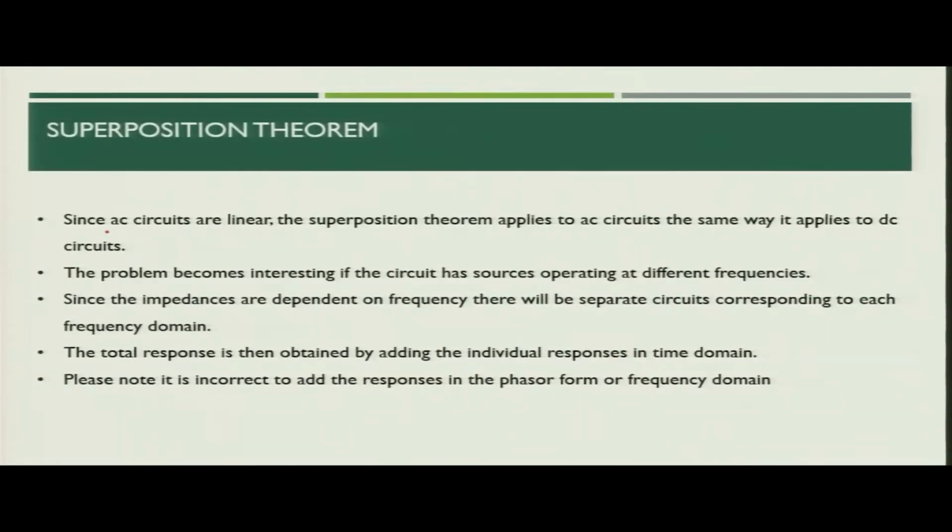Now, as an AC circuit is also linear, you can utilize the superposition theorem in the same way as you did in the case of DC circuits. The important thing to keep in mind is that the processing of the superposition theorem is a little bit different in the case of AC circuits, because your source operating frequencies can be different.